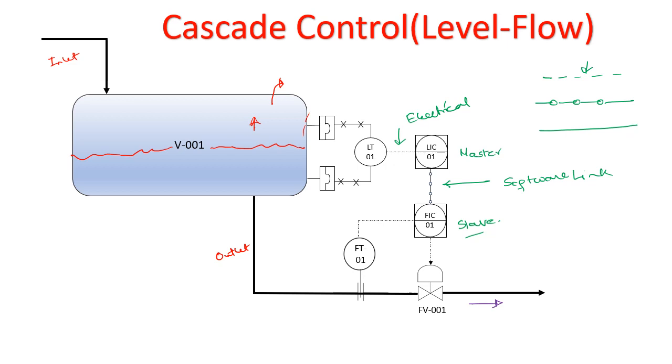So if you are still confused, you should go back to earlier lectures and see what is the significance of the different lines. This particular symbol is of an orifice and this is a globe valve. And this particular LT is a diaphragm seal LT. This signifies the diaphragm and this particular line signifies the capillary. Okay, so hope this is clear to you.